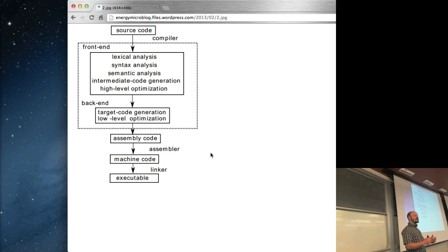Yes, you can do that. So in GCC then, a way of giving it a tip that, hey, this is really what I want to do is you can declare them as volatile. And then GCC will think, okay, you really want to do this subtraction here and I should not start trying to optimize this. So there are ways of doing these kind of things, but sometimes they can be hidden. You can do optimizations, and if there are multiple different levels of code that you have there, and then somewhere you have not a volatile declared, and bam, gone it is, and your code is gone. So then you have to go back into the disassembled code and see what did the optimizer actually do with your C code. Happens more often than you would think.